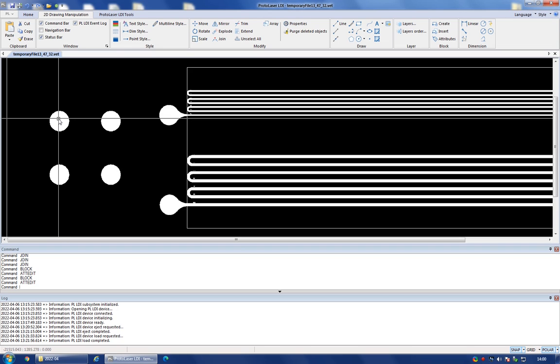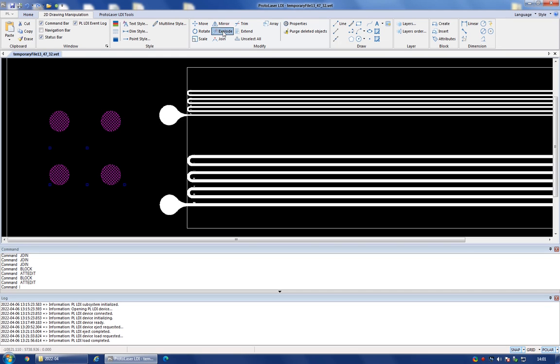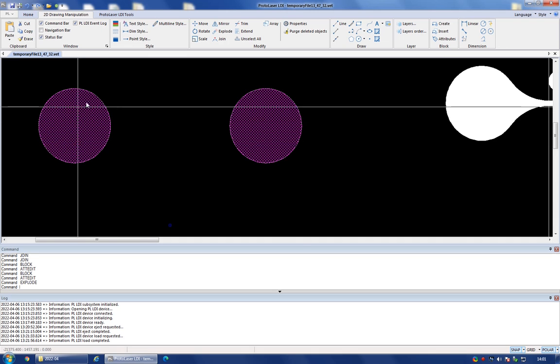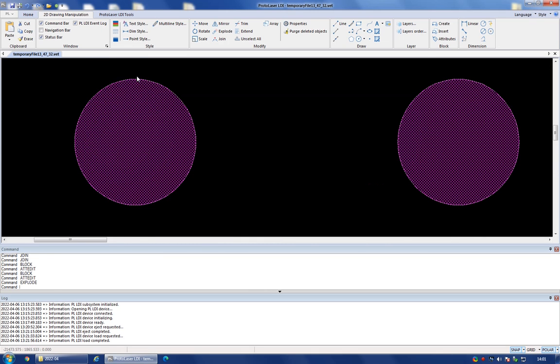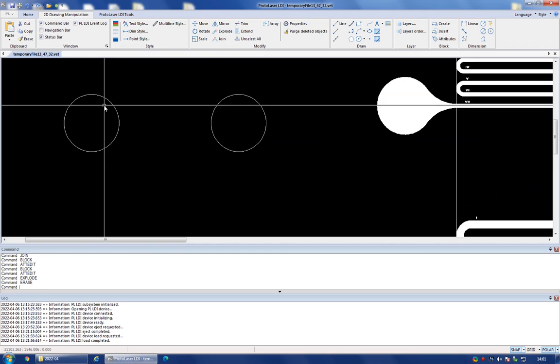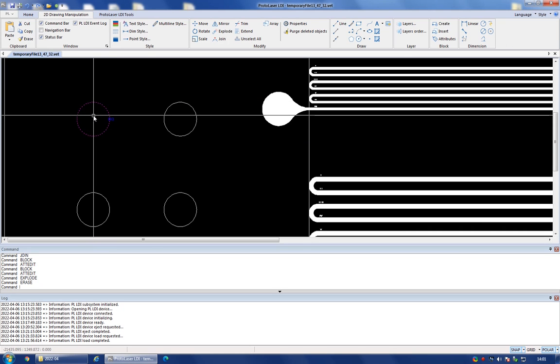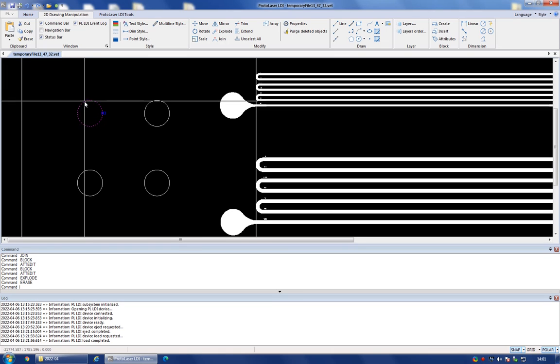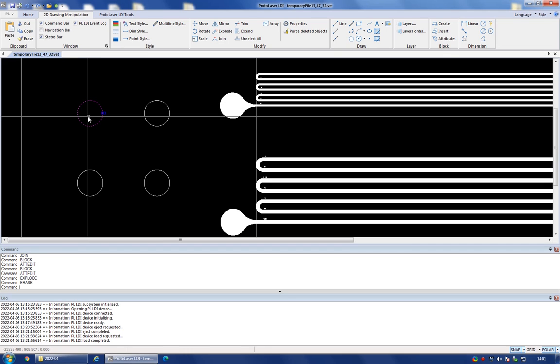If you wanted to do that, you would have to go revert the block creation. So you would have to select the block that you want to edit. You hit the explode button, and this will essentially break apart the filling, which is the block, from the shape itself. So now I can select the block. You see, I'm selecting all of these shapes, but you can see that there's also this white edge, which is actually the shape that has been used to create the block, and if I hit the delete button now, I have removed the filling and I'm left with the shape. So this is now back to the shape that I had in the beginning, and I can use this now and modify it and edit any position of any lines, and then when I'm ready I can recreate a block as I did it before.